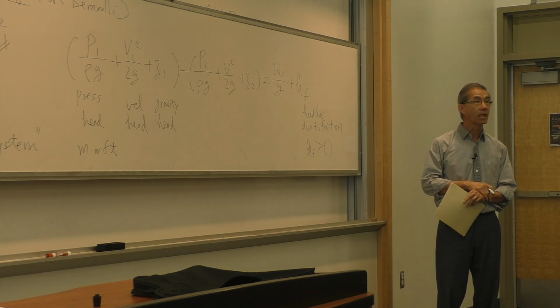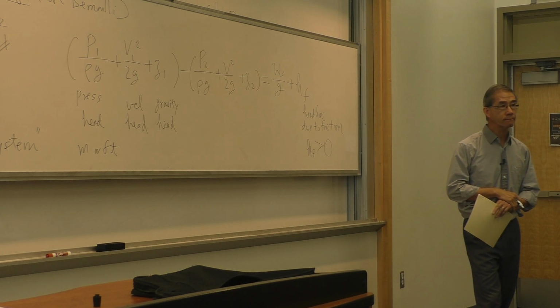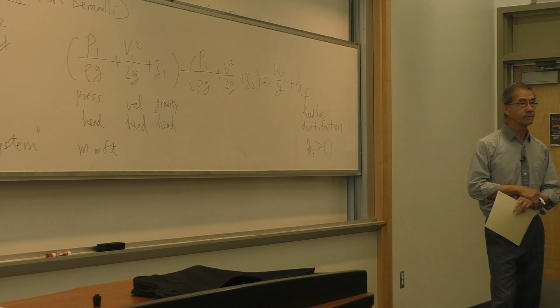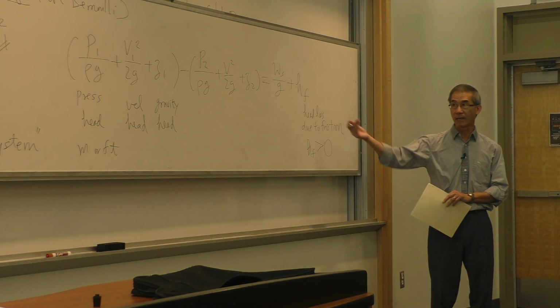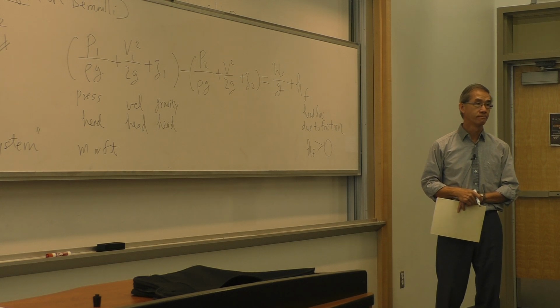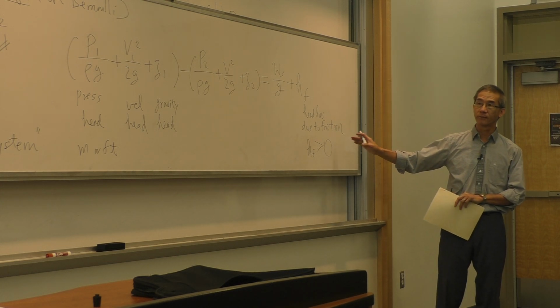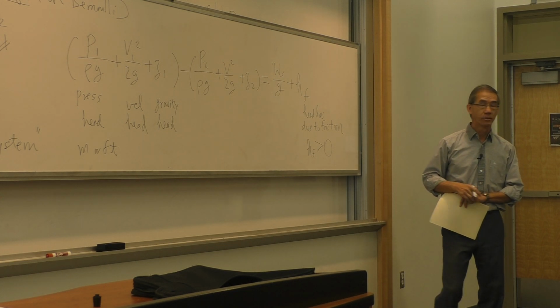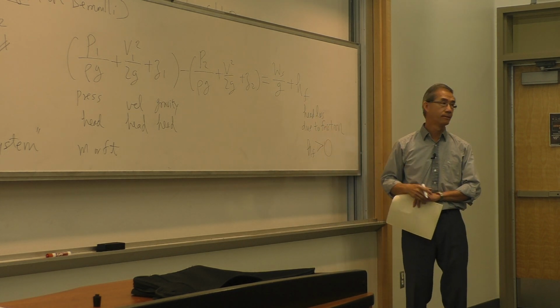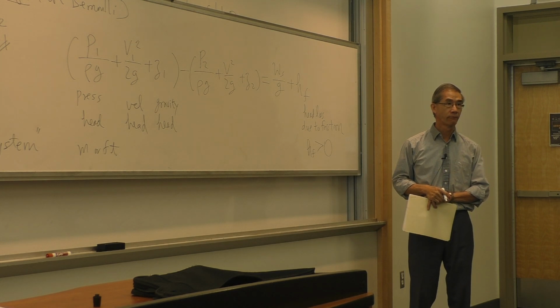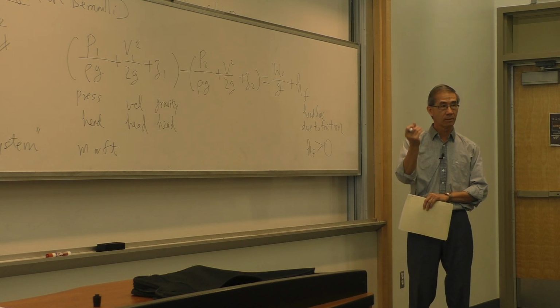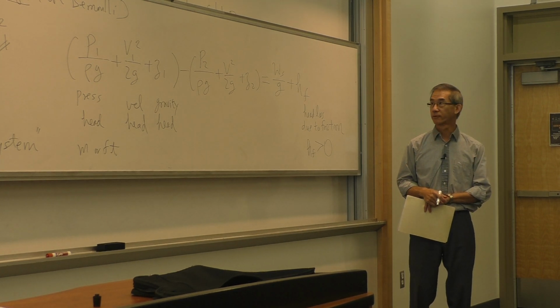Questions? Yeah? Do we assume adiabatic for all of this? Or will that come later? Yeah, that will be when I derive this equation. The answer is yes, but that will come later. Right now I want to cover enough for you to do the homework. So this is a positive quantity, always. Friction always causes loss. You need a pump to overcome friction.